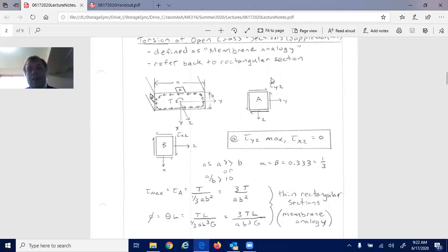In terms of a sign on the shear stress, remember, technically this would be a negative shear stress because on the positive y plane it's moving in the opposite direction from the positive z-axis, so that would be a negative. Over here on the positive x plane, the shear arrow was moving in the positive z direction, so this would be a positive shear stress. Again, that's really essential if you're trying to determine where the failure plane is, if you're doing the stress transformations to figure out stress on a particular plane.